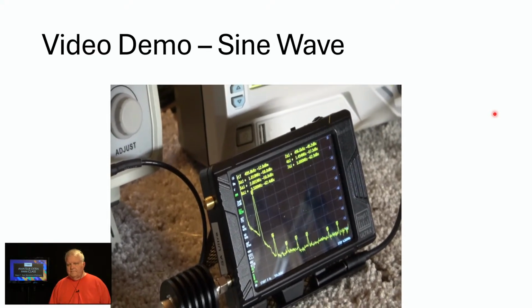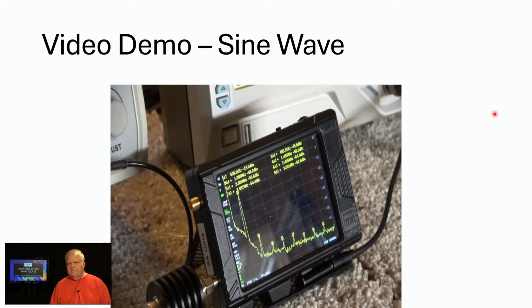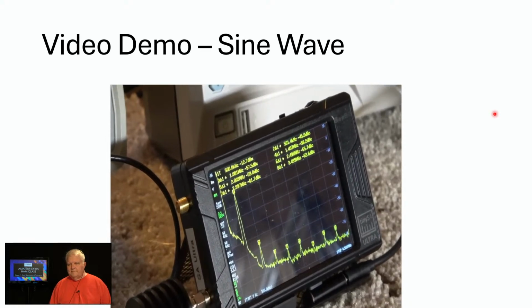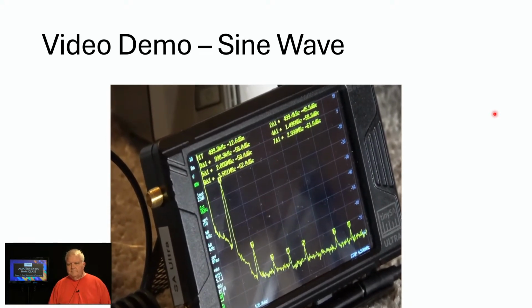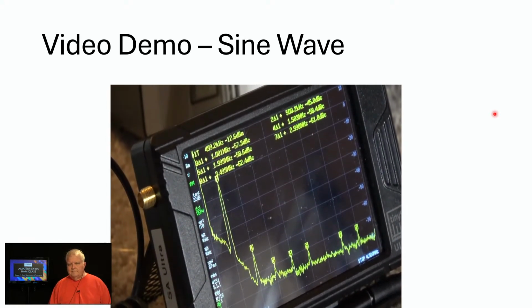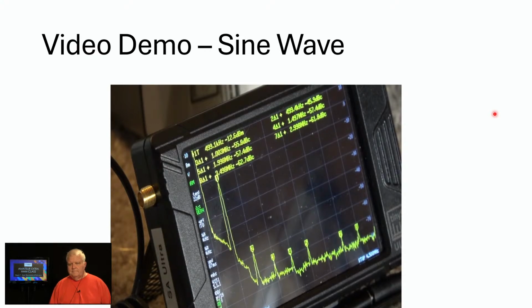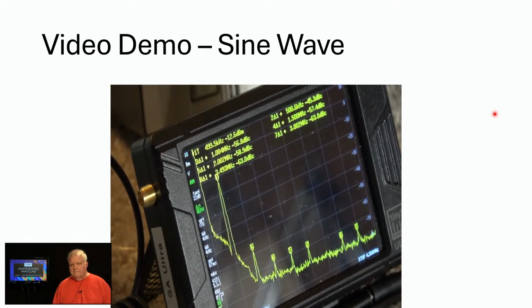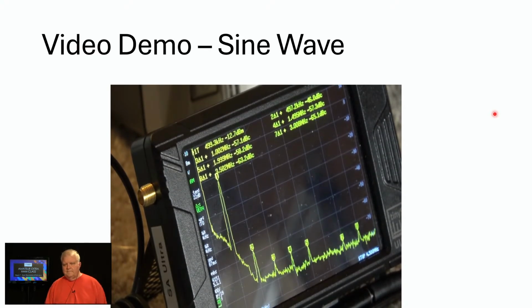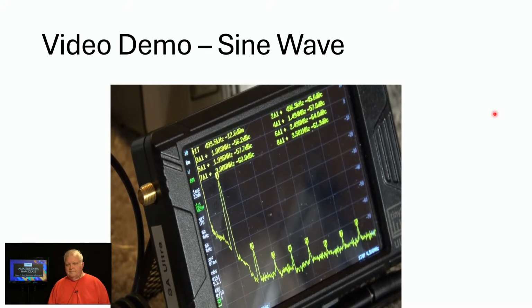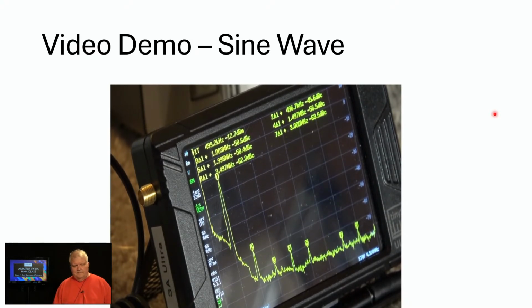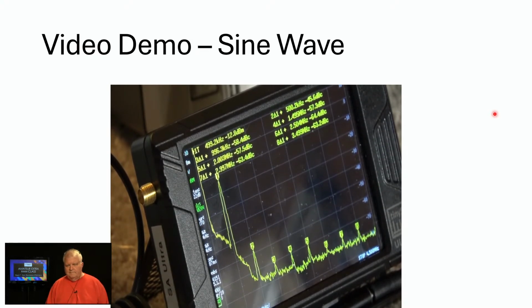And you can see on the spectrum analyzer the left-most blip going up there with the marker. That's the primary signal for the sine wave. And any harmonics, which are indicated by the subsequent markers, are very down, 60 dB below that carrier level.